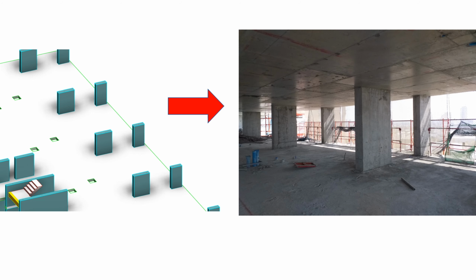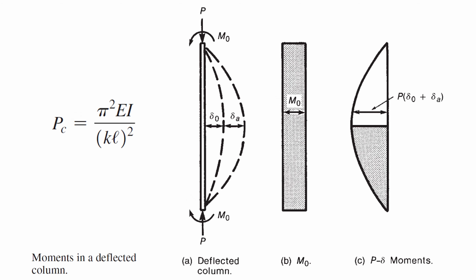Normally, the line element could be used to estimate the structural behavior of the column. However, in practice, the engineer might wonder if the shell element is more suitable for the column that is long and thin, similar to wall, than using the line element. The answer is yes, and no. I will explain why. The elastic buckling for any slender column could be explained using this equation.